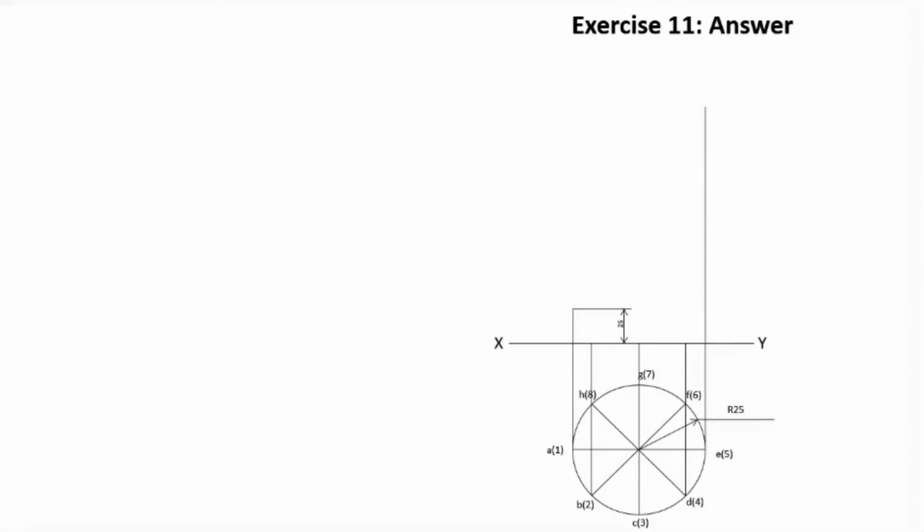So what we do is we draw sufficient length so that an arc with the center as this new point can intersect with this particular generator. So an arc of radius 100 millimeter is drawn, which intersects with the second end generator. Now join the point of intersection of the arc with the second generator with the initial first point that we obtained. So this is the section plane.